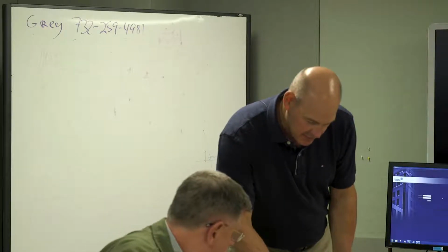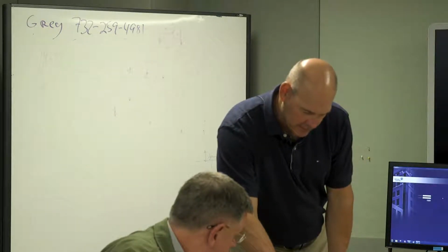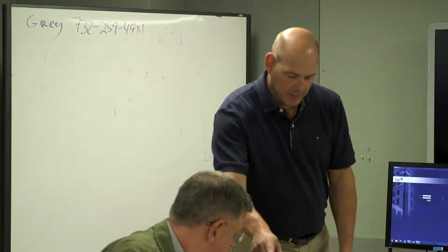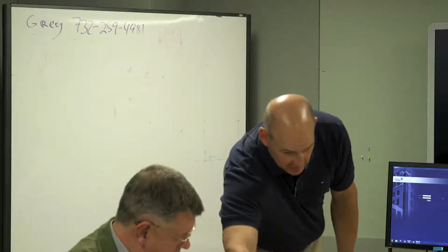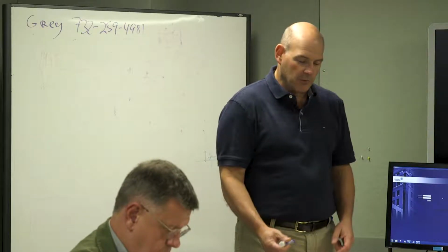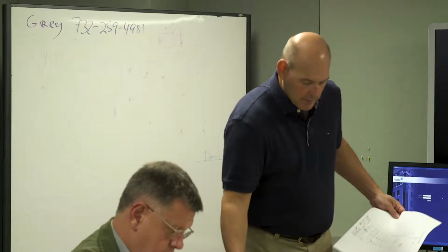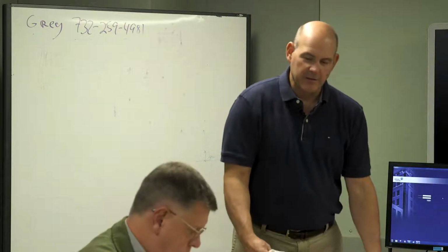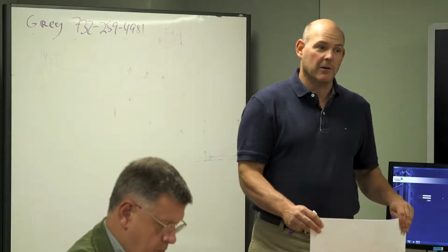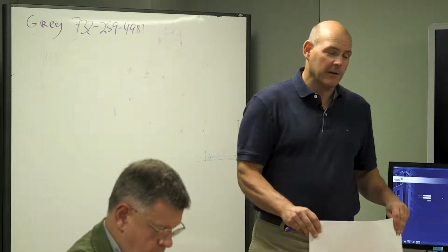So where it says field device and wiring and tubing, there'll be a detail number. That detail number reverts back to the page you were just looking at here. See how it says detail? F701. So you can go there, and if that detail was needed, it'll be there. So the intent is that this is your Bible. If you have questions on it, call me. You know, I'm here frequently.